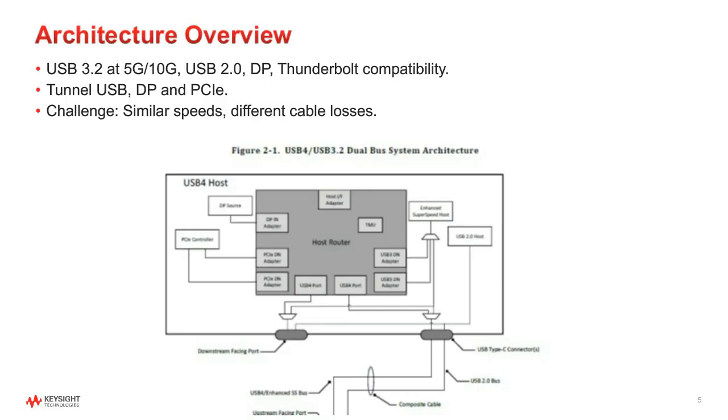There is this notion of tunneling, and we get these questions a lot, which is, do you have to test PCIe when you're implementing USB 4? So the answer is you don't test it at a Type-C connector. We do test the protocol for PCIe on a Type-C connector through tunneling, but there's no PHY.